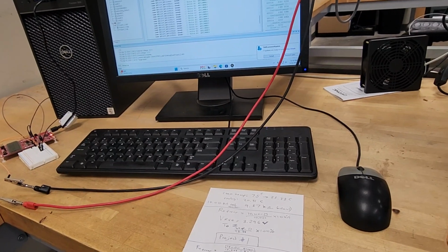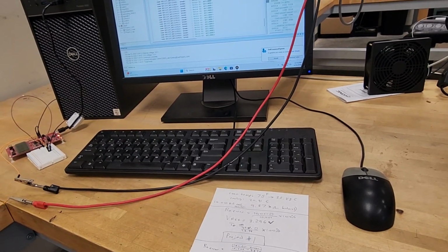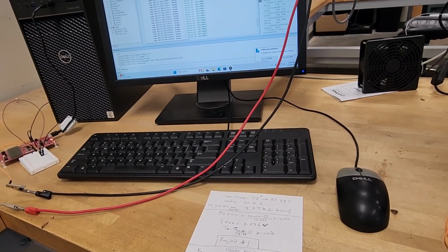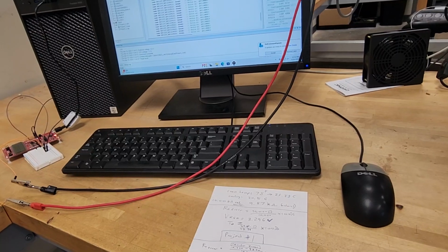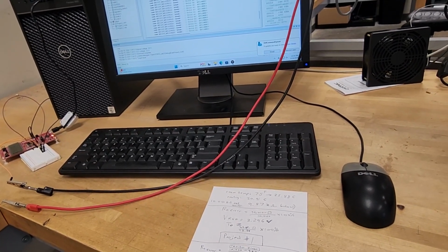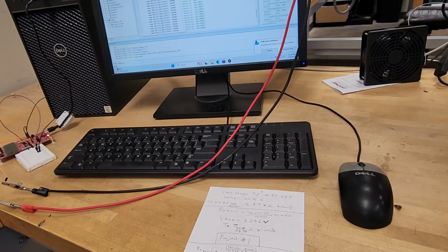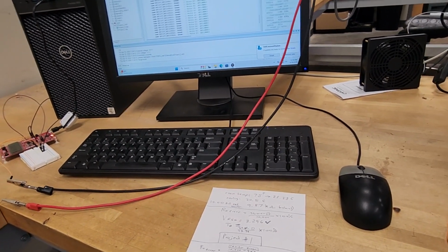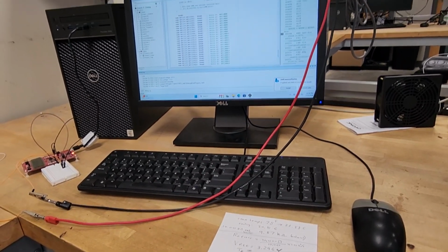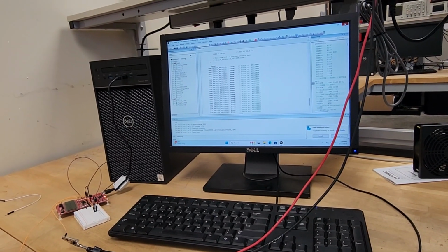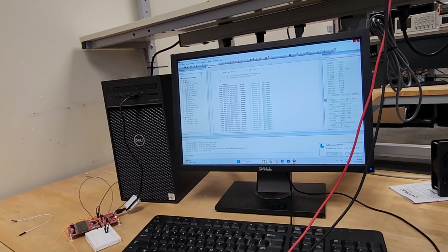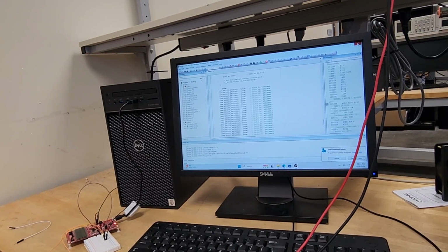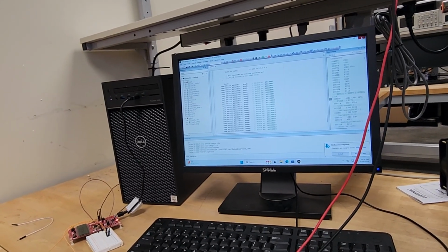One end of the resistors is tied to the 3.3 voltage supply on the board, and the other end connects to the thermistor. And the midpoint between them is connected to the MSP430's ADC, which is analog to digital converter input on pin P1.3. As temperature changes, the thermistor's resistance changes, which causes the divider voltage to rise or fall. This changing voltage is the electrical signal to the microcontroller that the microcontroller uses to determine temperature.